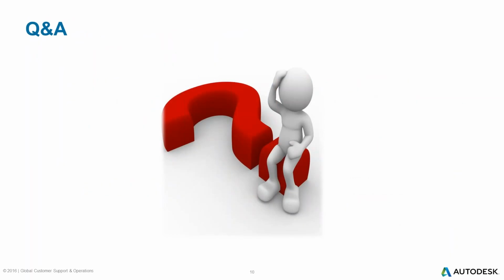And let's see, do we have any last questions before we call it a webinar? We do. We actually have a few more, some nice ones that came in here. So one of the questions is, when you copy an object with constraints and paste it into another drawing, do the constraints follow along? Yeah, I think that just like when I copied the geometry from one point in the drawing to another point in the drawing, copying it to another drawing would be the same thing. So it would create a copy of all of the geometry and all of the constraints and bring it across.